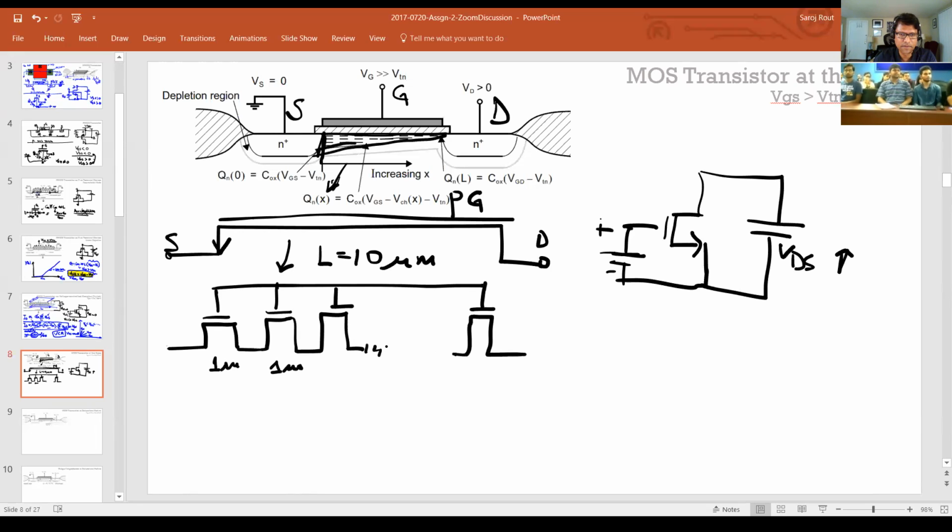So this is the same as this guy, just that these drain and source are like superconductors. They're just joined as if there is no resistance, because typically this drain and source will have the N plus type and all that, but in this case there's no N plus here. So this is just for argument's sake, okay? Now let's assume that these are small enough that the drain to source voltages are small. So let's say this is ground and let's put some gate voltage, let's say 1.5 volts here.